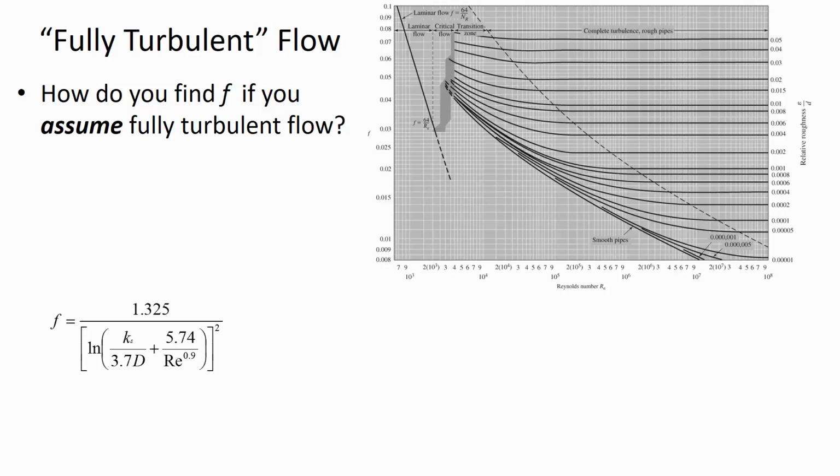So I said when you start having really high flow velocity, any additional flow velocity doesn't have an effect on the F value. Think from a numerical standpoint. A high Reynolds number is going to make the second term essentially close to 0. So as the Reynolds number keeps getting bigger and bigger and bigger, this second term becomes insignificant relative to the first.